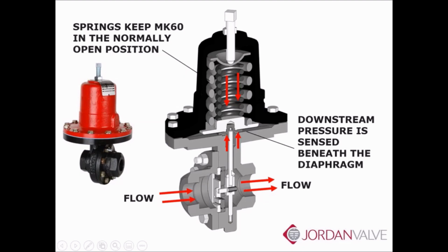When we install pressure regulators in the line, as we see here, these are threaded into the line, or you have a 150 or 300 pound flange in the line, and these are set it and forget it, right? Joe comes up here, he cranks this adjusting screw down, compresses the spring. You're going to have downstream piping and your gauge, right? The gauge could be attached to the regulator, or typically it's downstream. And if we want that set to 50 PSI under flowing conditions, he'll crank this down, wait till he sees 50 PSI and walk away.